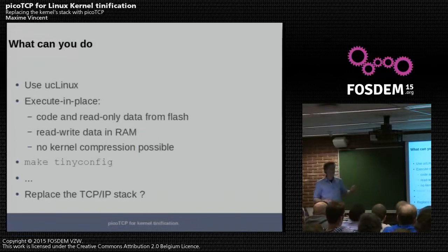First of all, you'll have to use uClinux because this CPU, which I just mentioned, has no memory management unit. So that's the first step you'll have to take. uClinux has other interesting additional features to run in an efficient way on small embedded systems. But it's also only kernel 2.6, at least the version we used right now. So it's lagging a bit behind, but okay.